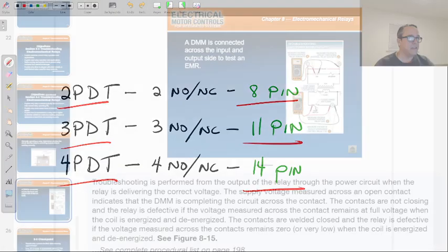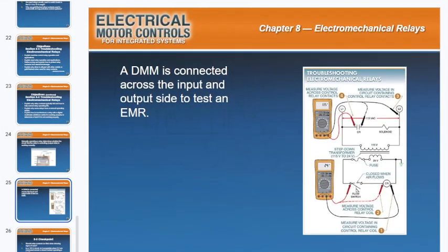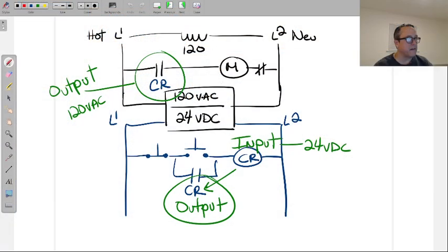So the last thing is, because they do mention it here, when we're troubleshooting, you have to remember that because you have a control relay where you could potentially be on 2 different circuits, you have to keep that in mind. Your digital multimeter might be on, like they have here, the 115 volt side, the contact heading to the solenoid, but the coil that's being controlled by the flow switch is on the 24 volt side of things. Just like what I have here.